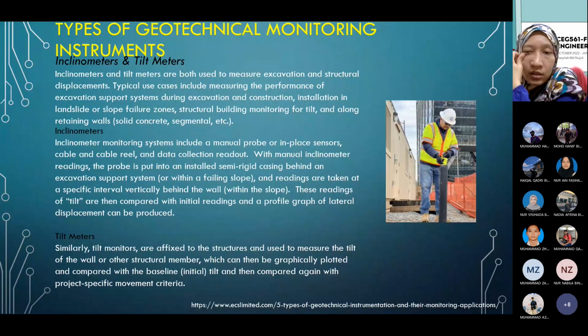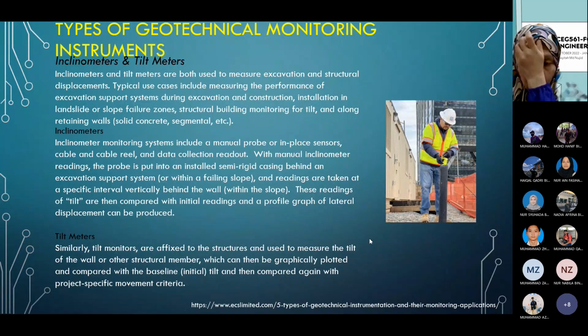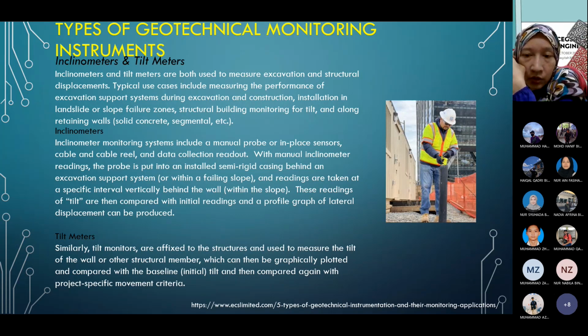So you can see the deformations on the soil, and also the movement and tilt of the building: does it move as you expected, or beyond your expectations? If the tilts or structure movement are beyond your expectations, you can do preventive controlling to tackle the issue.